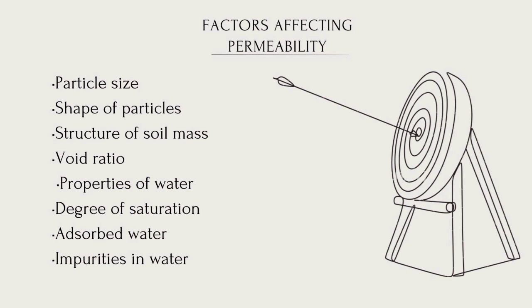Second, the specific surface area of the particles also affects the permeability. The higher the specific surface area, the lower will be the permeability. It is inversely proportional. The coefficient of permeability is inversely proportional to the specific surface area.